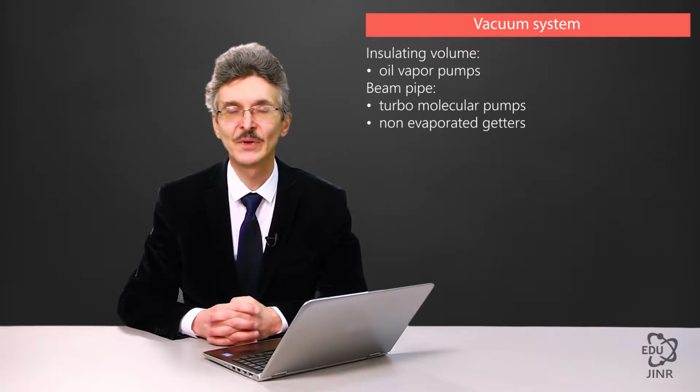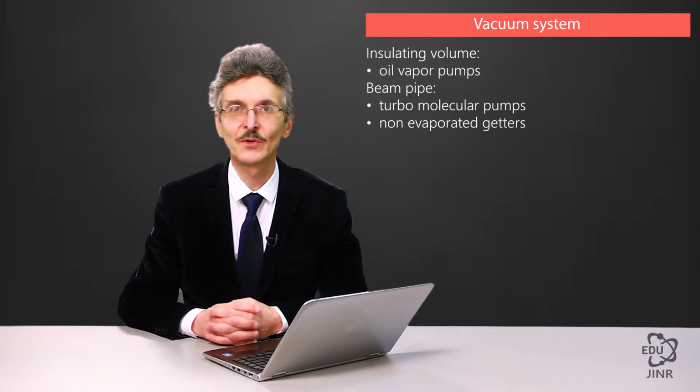In a superconducting magnetic system, where the vacuum chamber is at the temperature of the liquid helium, rather serious problems are posed not only by the production of the vacuum, but also by the manner in which it is measured. All vacuum meters are at room temperature and are located in the pipes outside the cryostat.